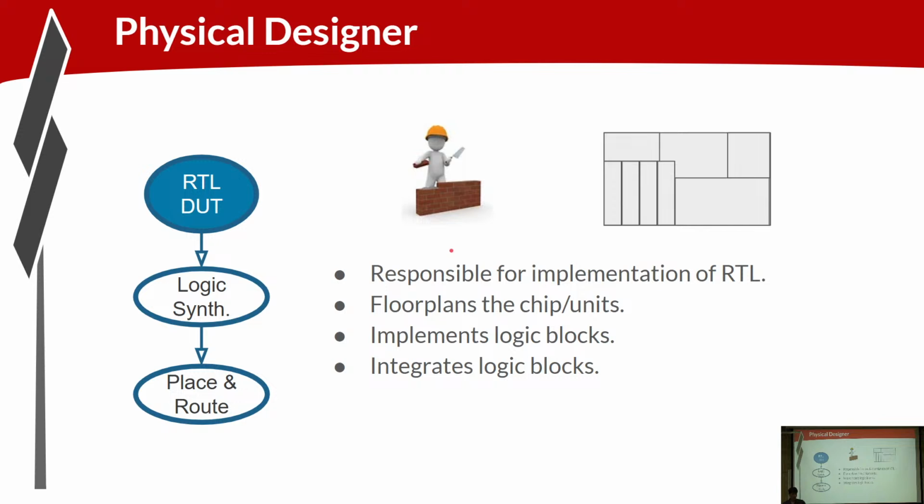So the physical designer will be responsible for floor planning the different units, and then implementing, running the logic synthesis, place and route on these different units, getting the connectivity all correct, and coming up with the implementation of the design.